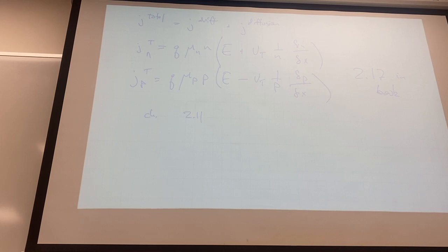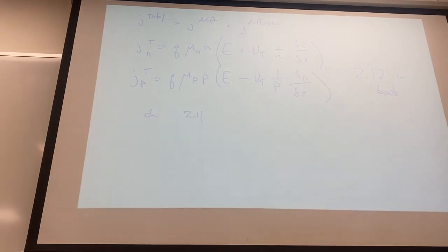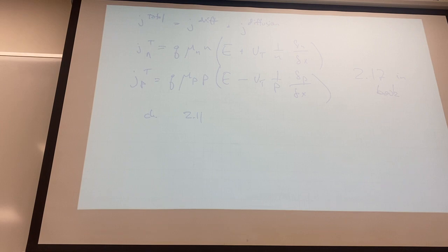All right, any questions about all this stuff before I, yeah, go ahead. So the VT capital, is it the thermal voltage? That's thermal voltage, that's right, yeah. We'll get into threshold eventually, but for now, all the VTs are going to be thermal for the next couple of weeks, probably. Yeah, but good instinct. All right, be skeptical of every VT and go, hang on, is this thermal or is this threshold? Yeah, good question. Just write VTH for threshold.